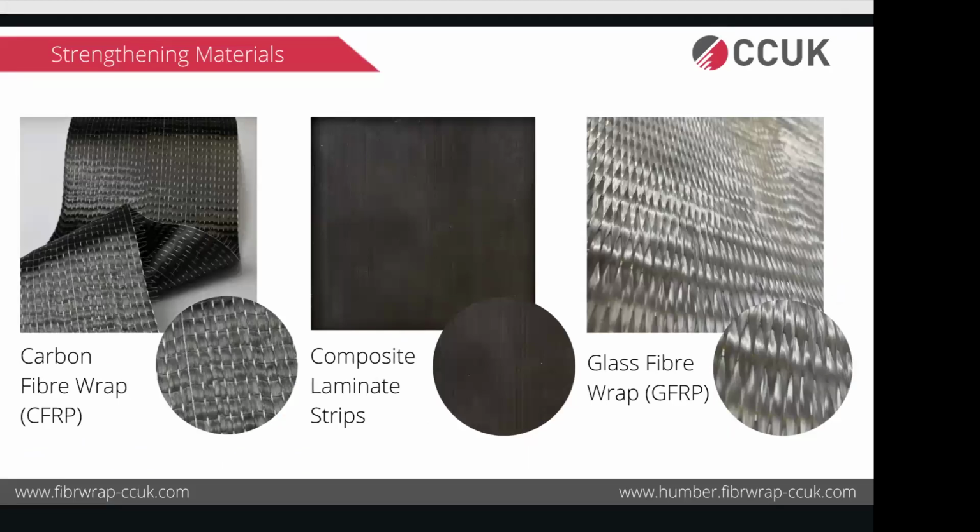Now, just to show you the material types, generally carbon fiber, or FRP, comes in two forms, especially for strengthening structures. One is a fabric system, which looks something like this. It's a dry fiber of carbon fiber, which comes on site on a roll along with the epoxy. So you can cut it in any size and shape you want, saturate it with the epoxy, and then apply it onto the structure in its wet condition. The application is called the wet layup method.